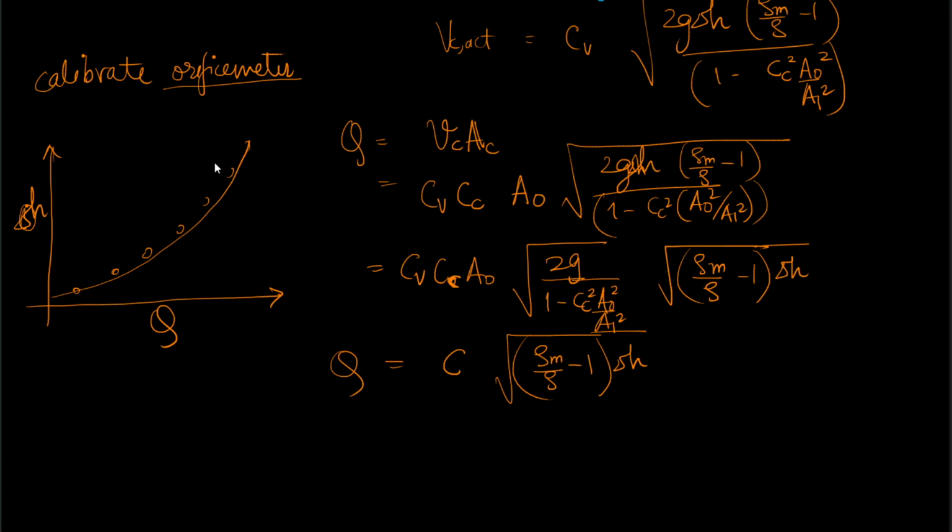So depending on the flow range that you anticipate, you will install a given orifice meter. You cannot use any orifice meter in any situation because calibration quickly goes beyond the idealized cases and reaches limits where there will be severe non-idealities. To avoid these non-idealities, one has to use an orifice meter of a certain area in certain applications.